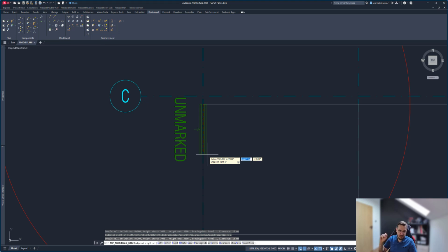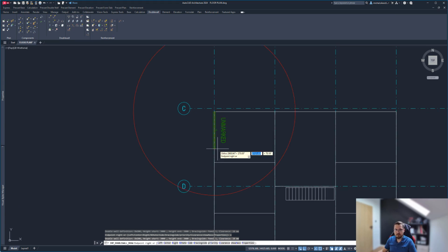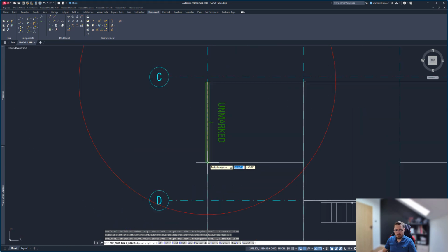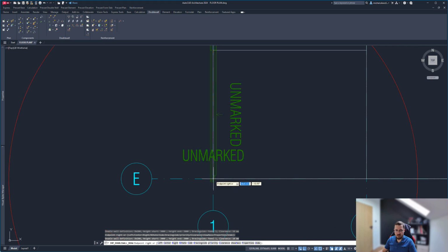What you can also notice is the arrow and the text, which shows you the internal side, or the side which you can brace. Basically the internal side of a double wall. So we can switch that with an S and a spacebar on the keyboard. So let's actually do that here like this. Okay, and what I'll do now is click here, and you see the red circle actually moves about once I click through points, right?